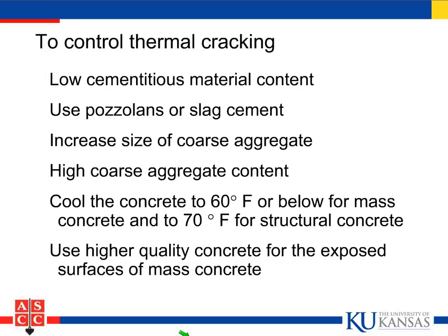And in case of when you're working with dam concrete, mass concrete, you have the ability to put a higher quality concrete right on the surface. So here we're talking about hundreds of thousands of cubic yards placement. The higher quality concrete goes on the surface. It can take the higher tensile stresses.